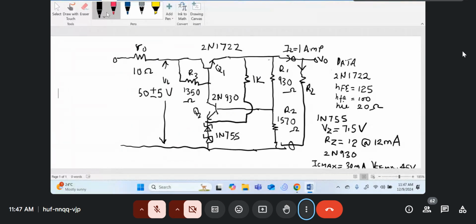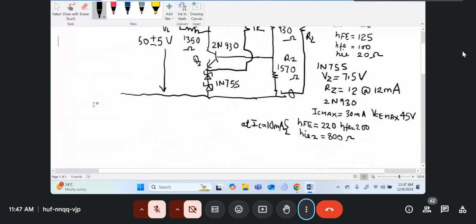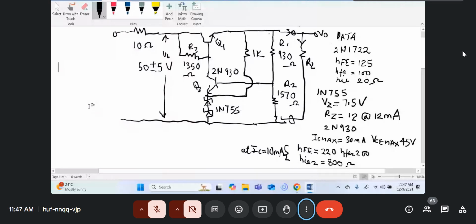I hope everybody has taken down the parameters that are there in the circuit. I said this is a very common circuit in audio high-powered amplifiers. For high-powered amplifiers, like the ones for PA, ranging from maybe 1,000 watts to 5,000 watts RMS output, Q1, you use many of them in parallel. And even the driver transistors will actually be a Darlington now. It won't just be one transistor.